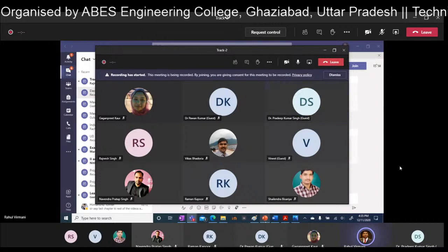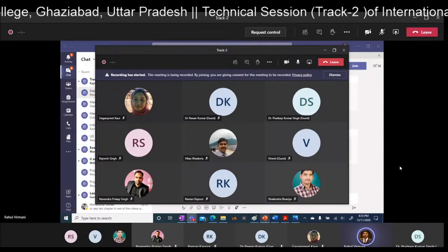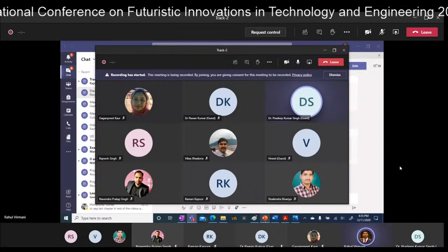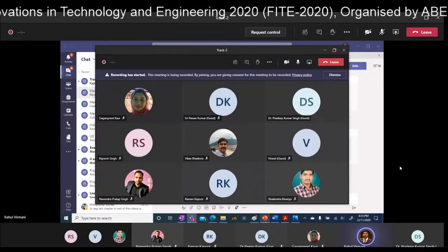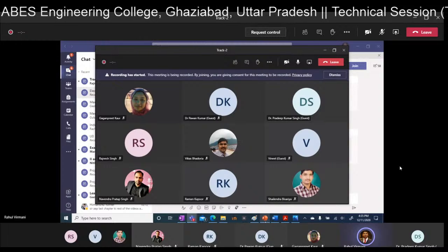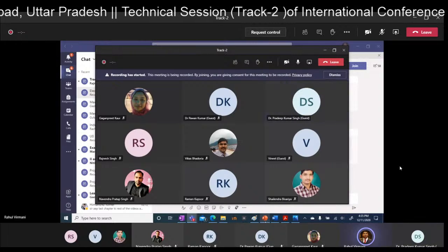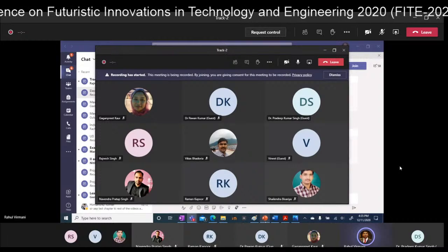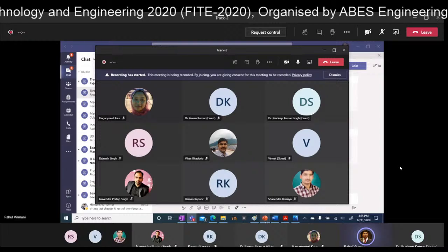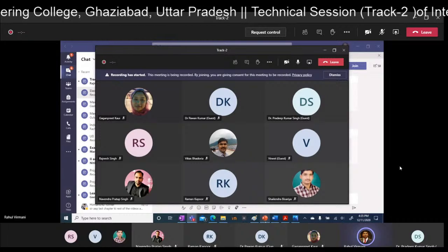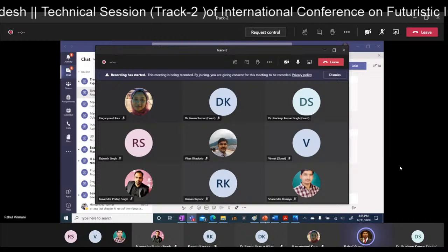Now these gains for these controllers have to be optimally tuned by some algorithm or some logic. Initially it was hit and trial, in which you put some values for KP, KI, and KD and then see whether the response is close to what you want. But nowadays, since there are a lot of tuner apps available in MATLAB, you can tune them. Or better, you can use an intelligent control technique such as fuzzy systems, ANN systems, or any kind of optimization algorithm.